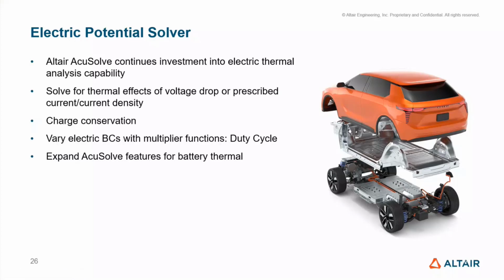The final new feature release for 2022 is the electric potential solver. With this feature, Altair AcuSolve continues its investment into electric thermal analysis capability. The feature solves for the thermal effects of a specified voltage drop or current, and the physics are based on the conservation of charge, and multiplier function control of the boundary conditions allows for simulating electric duty cycles. And this feature further expands AcuSolve's battery thermal simulation capability.